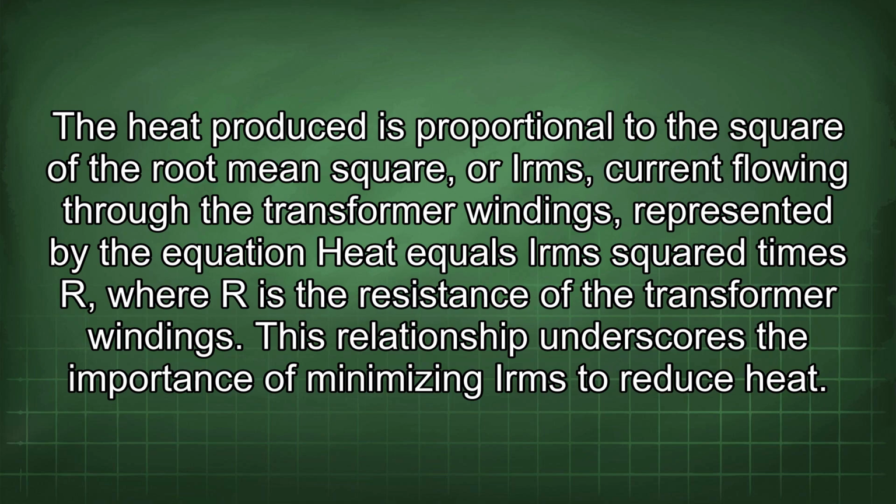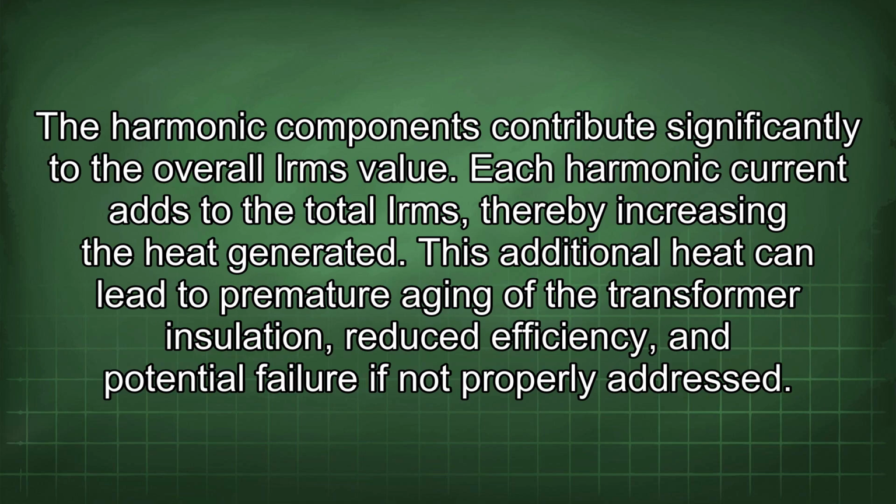This relationship underscores the importance of minimizing I_rms to reduce heat. The harmonic components contribute significantly to the overall I_rms value. Each harmonic current adds to the total I_rms, thereby increasing the heat generated. This additional heat can lead to premature aging of the transformer insulation, reduced efficiency, and potential failure if not properly addressed.